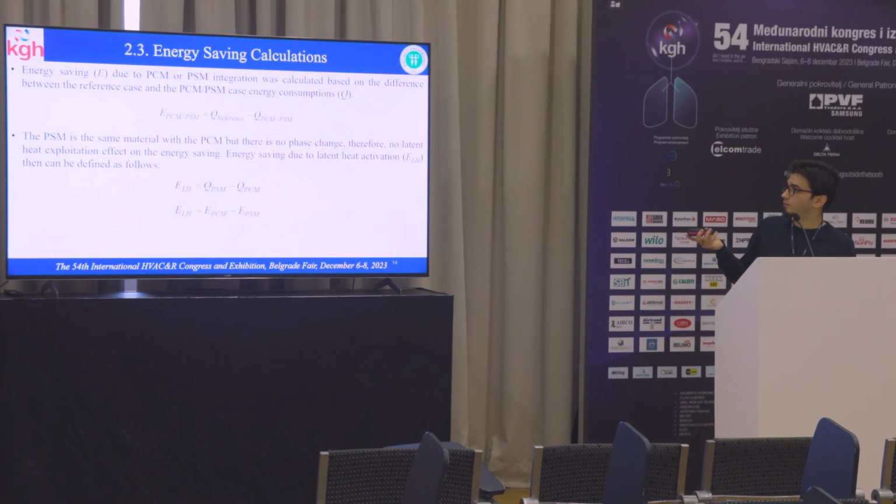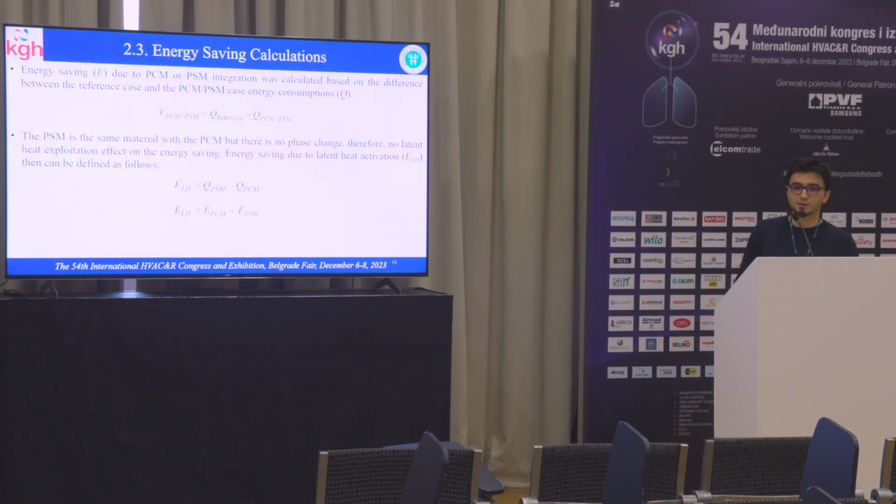The energy saving due to PCM or PSM integration was calculated based on the difference between the reference case and PSM case energy consumptions. The PSM is actually the same material as the phase change material, but there is no phase change, therefore no latent heat exploitation effect on the energy saving. When we use phase change material, we use energy by sensible heat, latent heat, and also thermal resistance of the material. The PSM has the same thermal resistance and the same sensible heat capacity as the PCM.